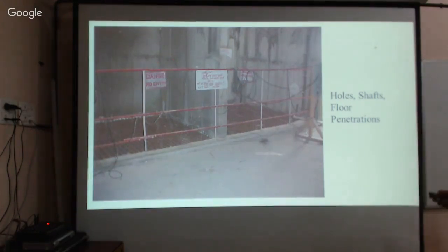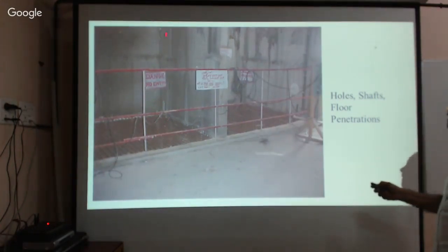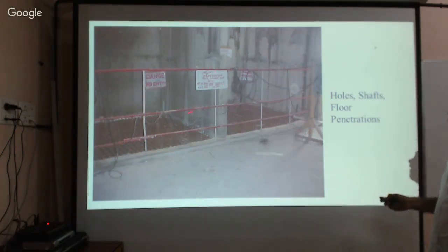Now this is the shaft. Shaft means lift duct. This is the lift duct. It is compulsory that this should be done, isn't it? Compulsorily at each and every floor we need to provide the guard. This is not a rail guard. Sometimes it will be covered with masonry up to a certain height, 2.5 meters or 3 meters. Now it is compulsory we must do it. Otherwise, people working on the floor may unknowingly get in and fall down, which leads to an accident. Therefore, let us be careful.